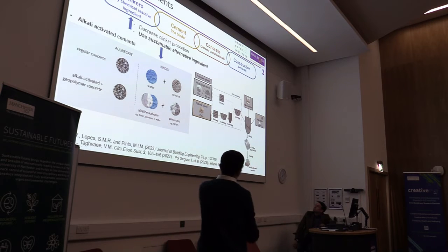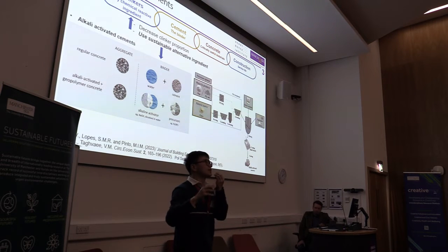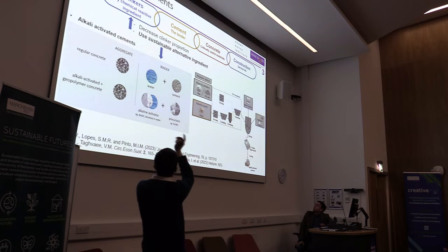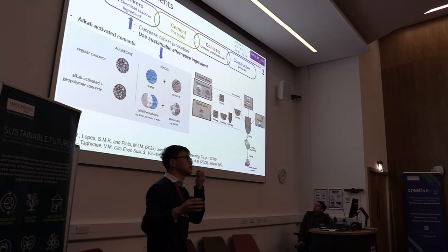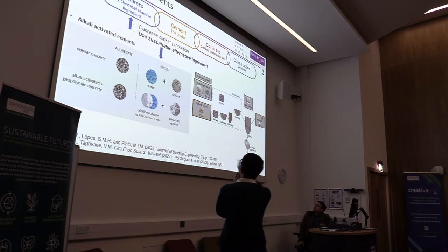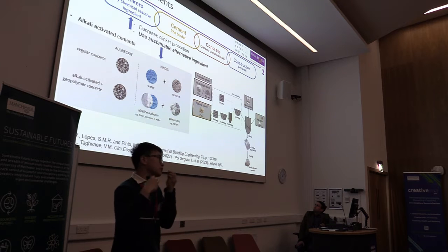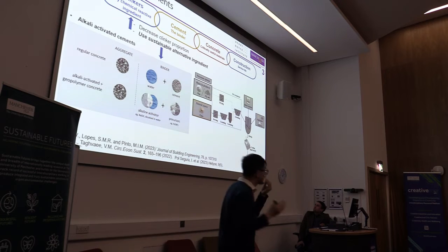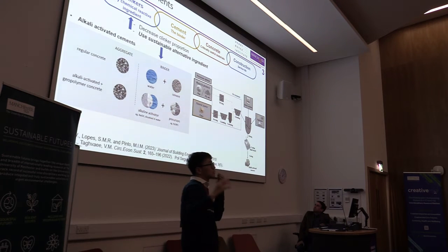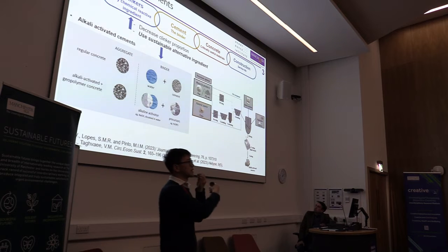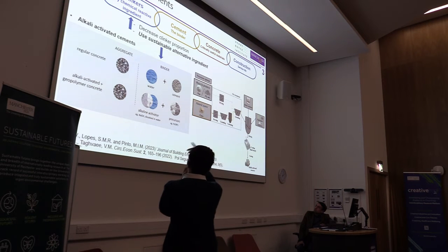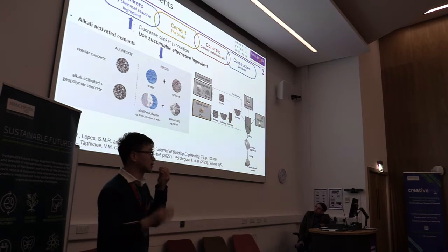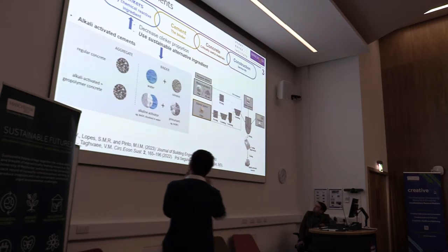From the clinker aspect, if we can cut the carbon dioxide emission from this part, of course we can cut a lot of carbon dioxide emissions. The first solution is to decrease the proportion of clinker used to produce cement. Yes, we can, and a lot of people are doing this. But the second way is to use sustainable additive ingredients to produce cement, replacing the clinker, the raw material.